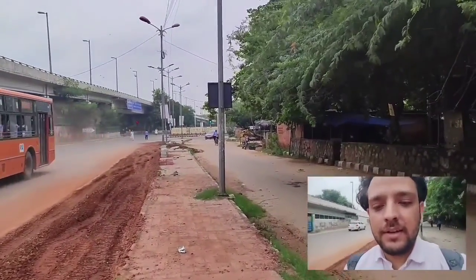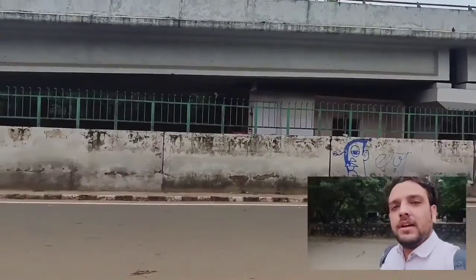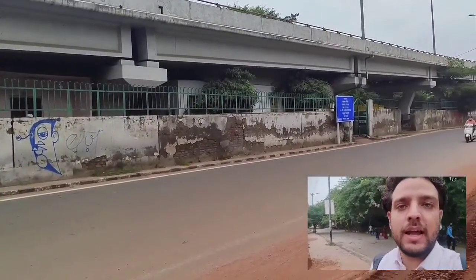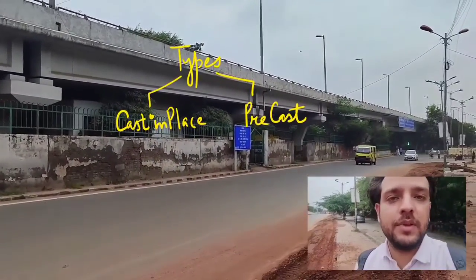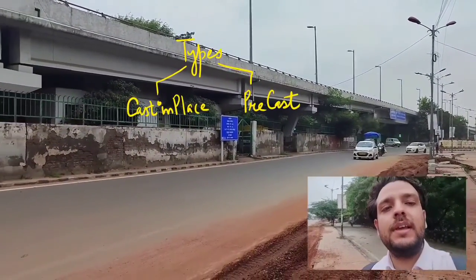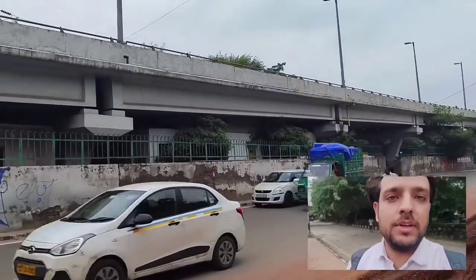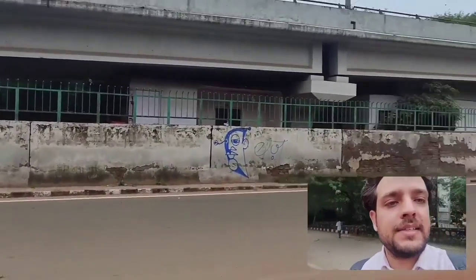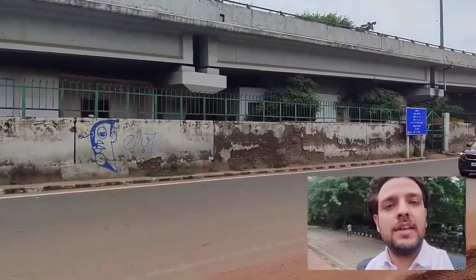Now we will see the various types of flanged beams, that is T-beams, in industry. From the ground, there are 2 broader categories. One is cast-in-place beams and another is precast beams. Cast-in-place means everything, the deck slab as well as the beam, will be monolithically cast over the pier caps, and all the shuttering and formwork will be arranged suitably. However, in precast beams, your girder may be cast at a casting yard on the ground, and then lifted through suitable capacity cranes onto the pier caps.